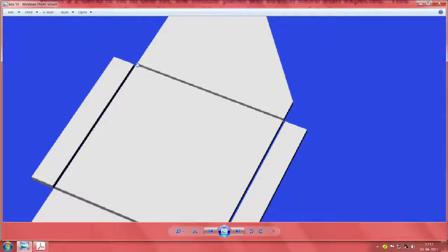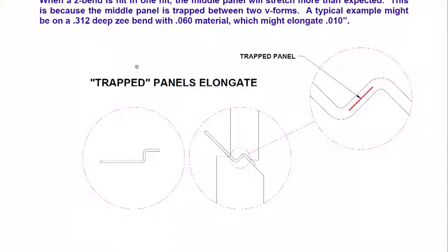This width cannot be this much, it needs to be a little smaller or it needs to be bigger. In case it is overlapping this, it needs to be two thicknesses wide compared to this. In case it is coming inside, you need to have probably two thicknesses smaller. Otherwise, we end up with a corner which is not filled, and I can see edges of both the sheets in the corner. This is in one shot, if you are trying to make any of these angles.